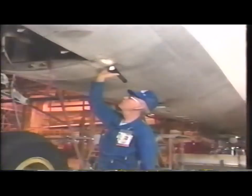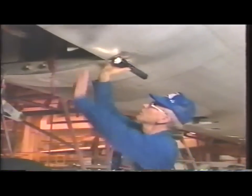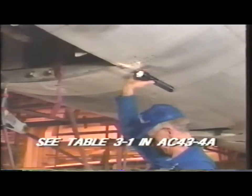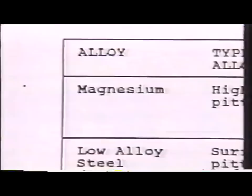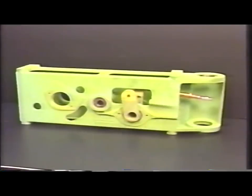Other metals commonly used in aircraft construction require special preventive measures to protect them from corrosion. The information which follows summarizes Table 3-1 of your AC 43-4A. Magnesium is the most chemically active metal used in aircraft construction and is highly susceptible to pitting. Corrosion on magnesium initially appears as white spots on the metal, and with time these spots can develop into white powdery mounds of corrosion product. Magnesium always requires a protective coating. It is usually painted and protected by either chemical conversion or electrolytic processes.